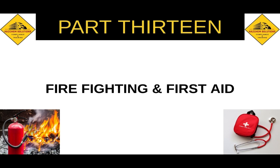Remember that vehicles must be properly registered and licensed. They must undergo a roadworthy test, and this must be done annually. They must get a roadworthy certificate. They must also be fitted with the prescribed signage and equipment for the dangerous goods they will be transporting. Remember, once signage and equipment have been fitted correctly, the vehicles must be registered at a relevant local license department as Category D. And once that's all done, you then take the vehicle to your nearest fire department, so that you can get a dangerous goods transport permit, which will be valid for 12 months.